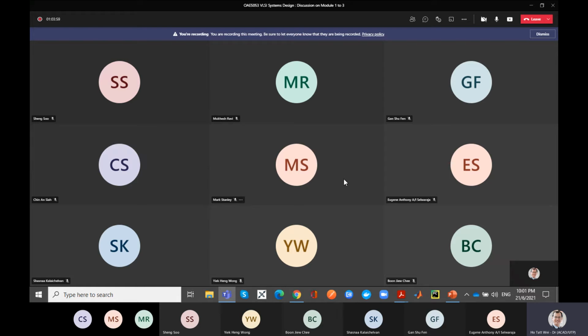This is IC design. This is where all the things can break. And to be quite frank, a place and route algorithm is not guaranteed to converge. So the fact that you have a design that managed to be placed and routed, sometimes it's a bit of a miracle. I would caution you that if you start throwing a lot of constraints, sometimes your place and route may not converge into a design. That's when you have to help it a little bit, like change the constraints, like increase the area, that kind of thing.